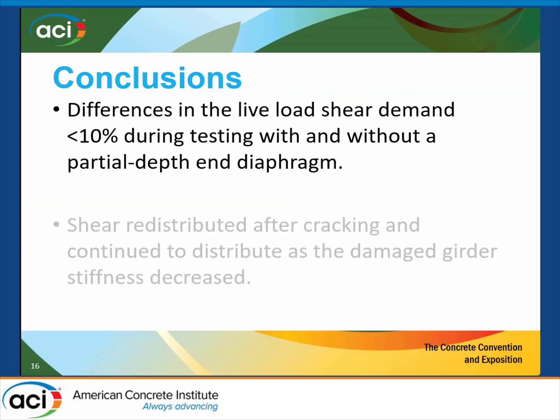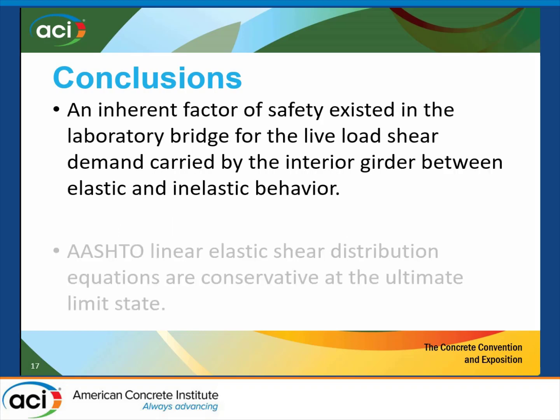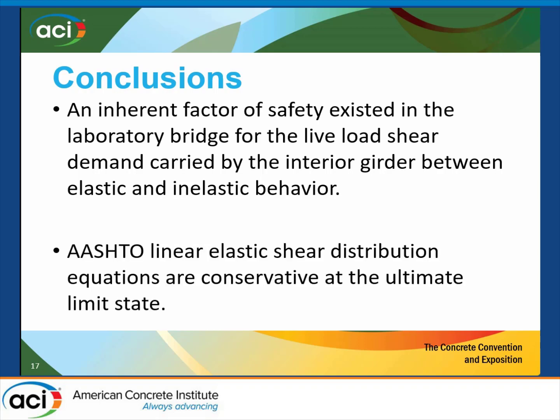So the conclusions that I found here are the differences in the applied load were only 10% or less, considering with or without a partial depth end diaphragm. There was definitely shear redistribution after cracking as that damaged girder continued to be damaged and head towards failure. There was an inherent factor of safety that's really tough to quantify because we're not applying a truckload like design codes do, but there was definitely an inherent factor of safety from elastic behavior to inelastic behavior, which means that these linear elastic shear distribution equations were conservative, right?